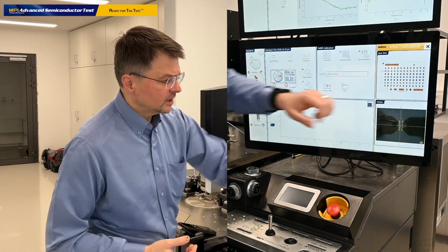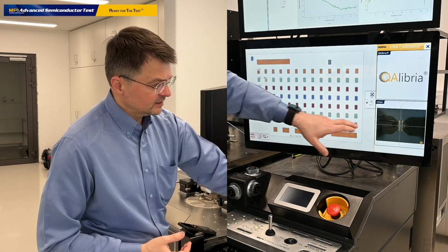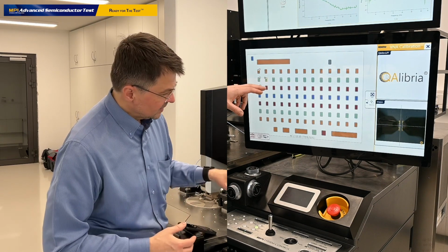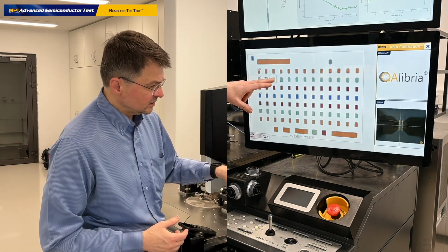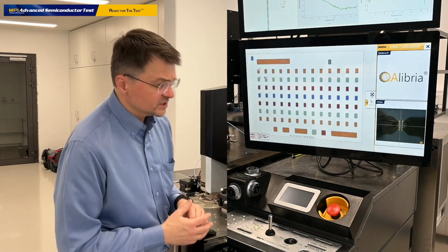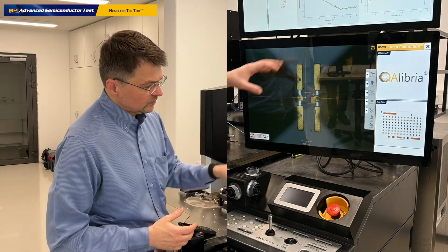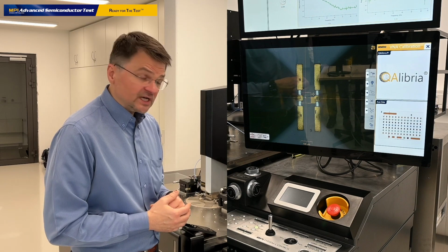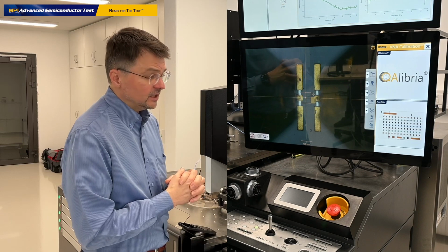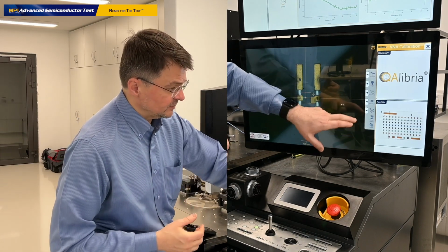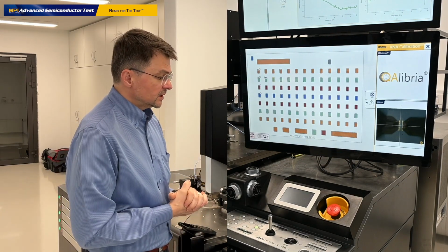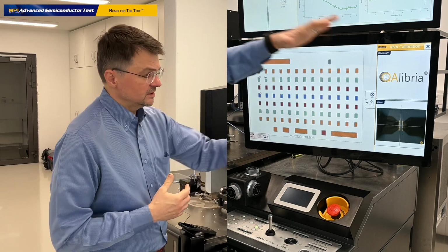Let me check the next calibration standard. So I select here the functionality move to calibration standard, and this is the load. And if I move here, this is another load standard, and if I have a look on the screen, it's been used a couple of times, but it looks like the standard is still of very good quality, and if I select it for the calibration process, I should have successful calibration results. How to do it? The selection of the calibration standard can be executed through this navigator tool.